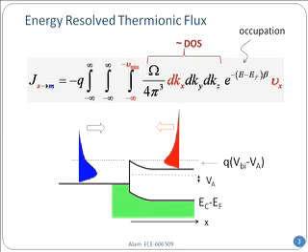As a result, I cannot simply integrate them all out and call this the density of state multiplied by this velocity. You see, the reason is, of course, not all those electrons going in x, y, and z direction are going to cross the junction, and they will not contribute to the current. So I write it resolved in x, y, and z, and look at the velocity I have multiplied with, Vx, because that is the only part of the flux that is going to contribute to the current.